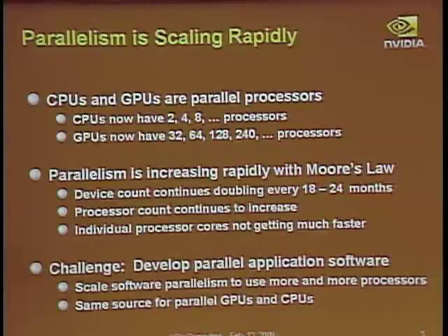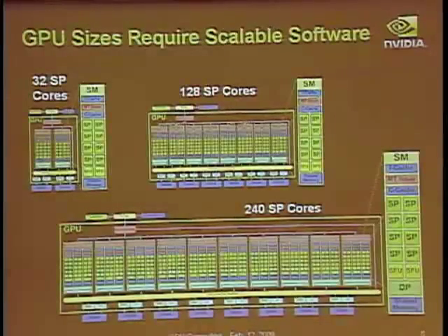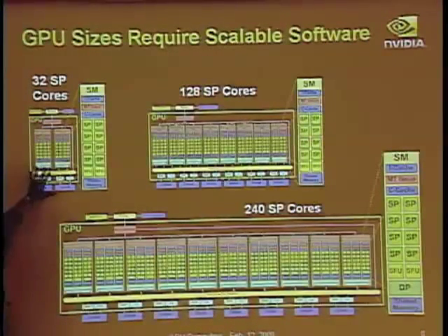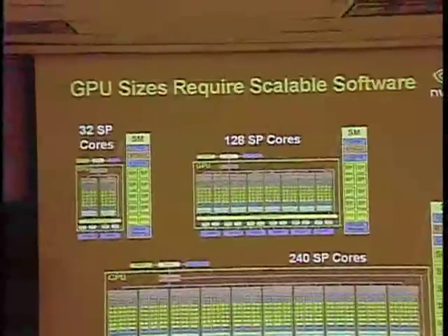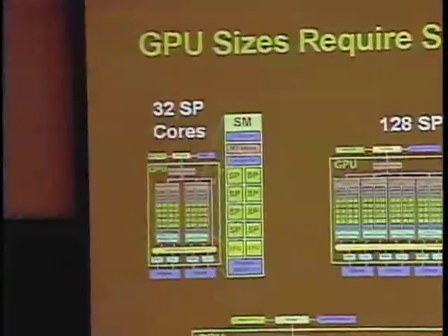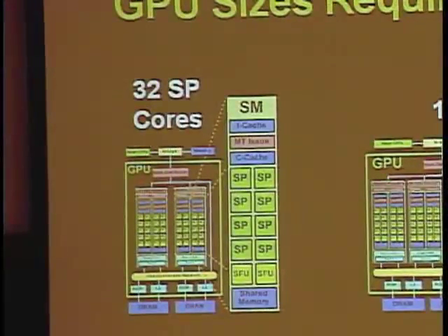So what that means from a software perspective is, how the heck do you use all that parallelism? I'd say the biggest problem we see in people trying to write CUDA programs or OpenCL programs is that they start off and at first blush they just don't have anywhere near enough parallelism, not even close. Let me show you why. Here's a little GPU. This has 4 SM processors. Each SM has 8 scalar processor cores in it, so that's 32 cores altogether. That's a small GPU, but some of the laptops we sell today have half that much.